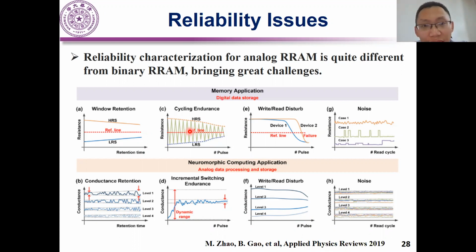But for analog switching, it is very complex, especially for the endurance test. We still do not know how to make a good characterization, because if you change the conductance little by little and do this full window switching, it is still not similar to the training case.